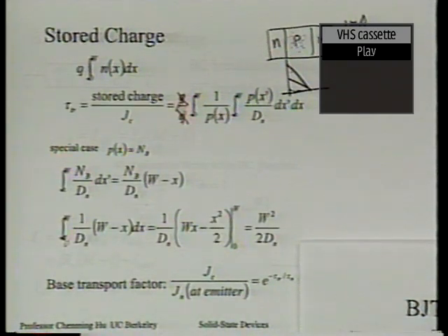I'd like you to think a little bit about that. What does that mean? What is the meaning of recombination lifetime? If I all of a sudden introduce 100 excess carriers into a piece of silicon, and if I know the recombination lifetime is 1 microsecond, does this mean that all these 100 carriers will live, no one is lost by recombination up till 1 microsecond, and at that moment, all of them on cue suddenly recombine and die? Is that the meaning of recombination lifetime? What do you have as meaning of recombination time in your mind?